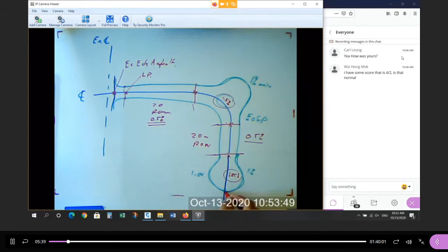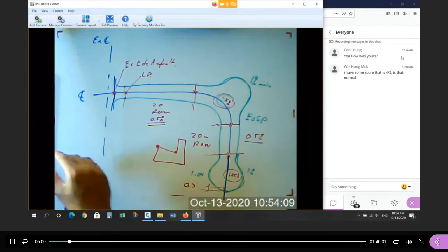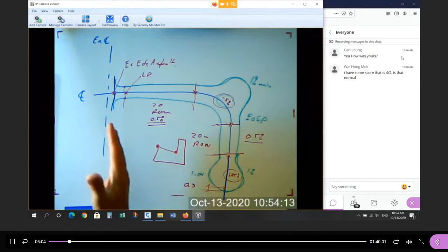And down at the end here, remember, not the gutter line, but 0.3 meters in. The last point on the asphalt is where that profile starts. Remember this dimension here is 0.3, which is your distance from edge of asphalt to gutter. Okay. So once we draw those points in plan, we can use Civil 3D to project those points from the plan to the profile, and then we have our station values for our profile design.